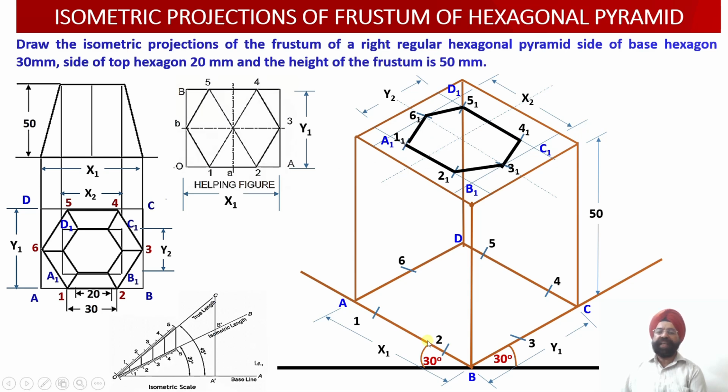Now the vertical edges, we can see which of the vertical edges are visible. Please check, 1, 1 and 1 is visible, 2, 1 and 2 is visible, 3, 1 and 3 is visible. Similarly, 4, 1 and 4 is visible. So these are the 4 vertical edges which are visible, but 5, 1 and 5 are not visible. Similarly, 6, 1 and 6 are lying behind, so they will not be visible. On the same lines, these 3 edges of the base, 4, 5, 5, 6 and 6, 1, are lying behind, so they are not visible.